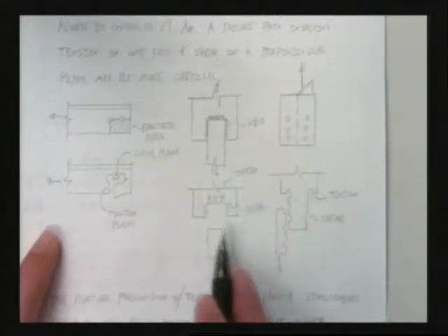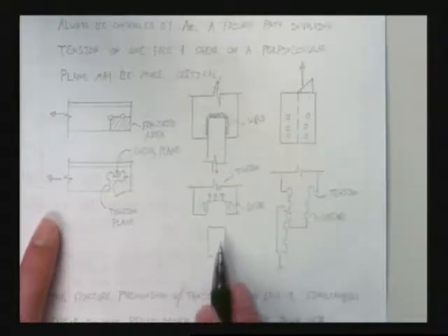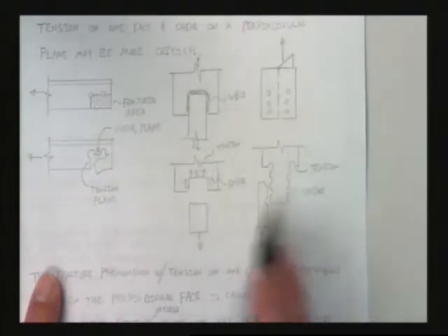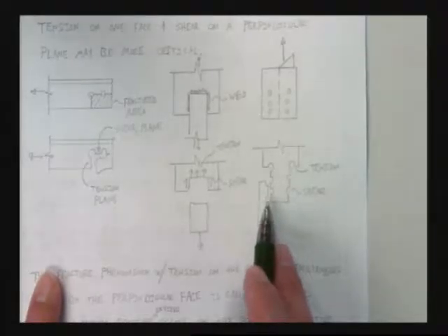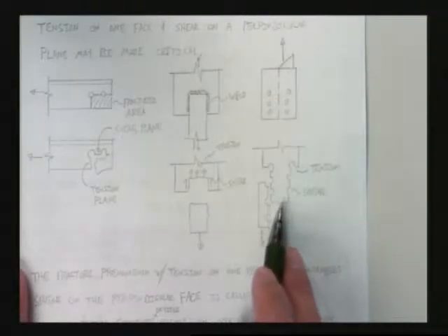Great. So we've got these welding failures that we talked about as well. It's a possibility for block shear. It could actually happen in the plate or in the base metal. We talked about some situation like this where you could actually have block shear on two different faces simultaneously, right? So which one's going to control? Well, the one that causes the lowest load for it to happen, right? Awesome.